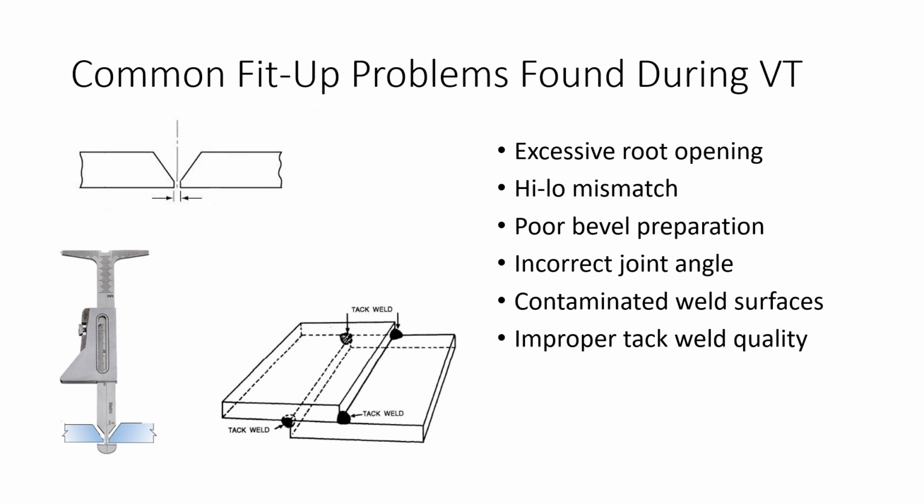And you can look at the tacks too. Maybe the tacks are just nasty, full of cracks and porosity, and they're going to consume these things into the weld or whatever. We could have issues there. These are the things that you need to look for.